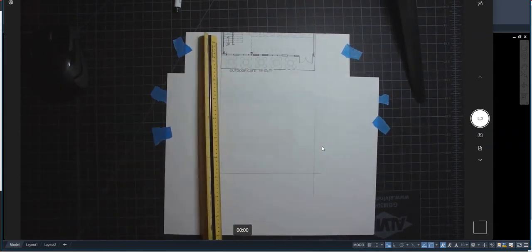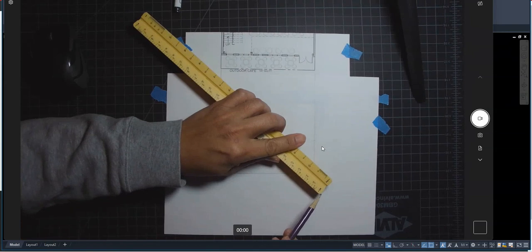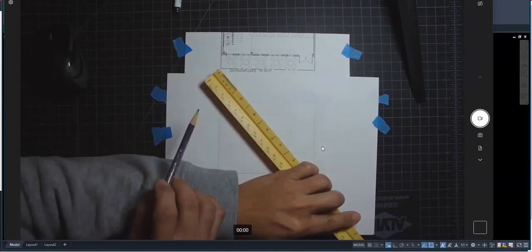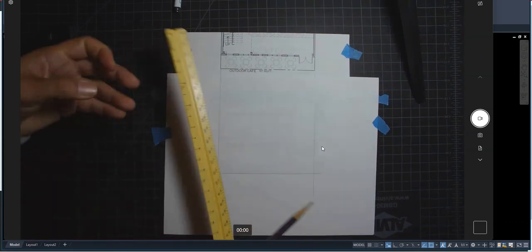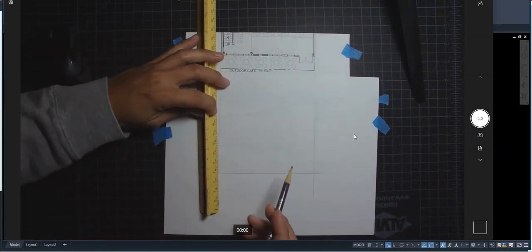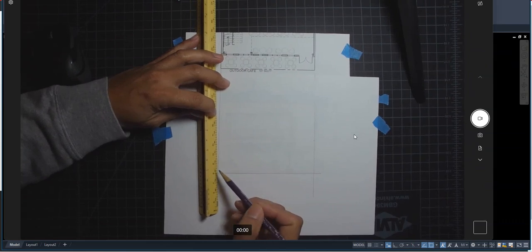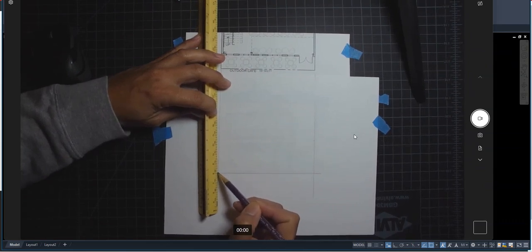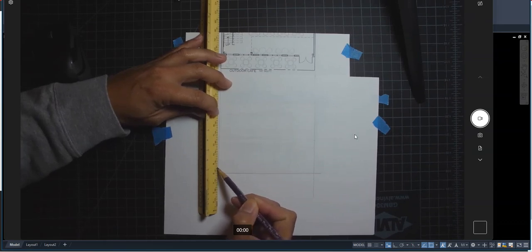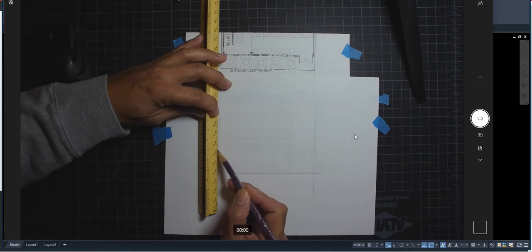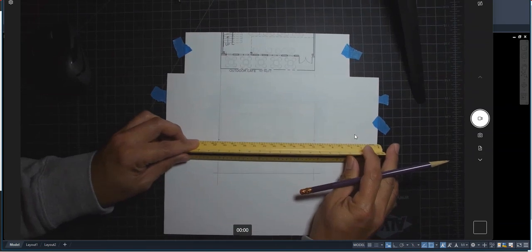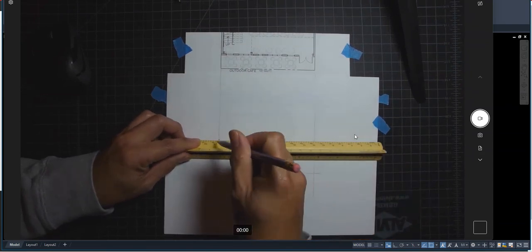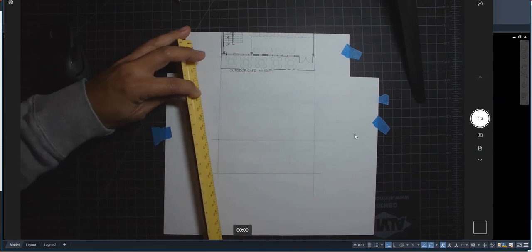And if you don't have a 1/8 scale, remember that 1/8 is half of 1/4. So whenever you see 1/4, you're talking about 2 feet really. So here, all I have to do is, 1/4 is 2 feet, but half of a quarter is a 1/8. So I'm also doing here 1, 2, 3, 4, 5, 6, 7, 8, 9, 10, 11, 12, 13, 14. So there's my 14. And there is my second floor line. Okay. And then I have another 14 feet.